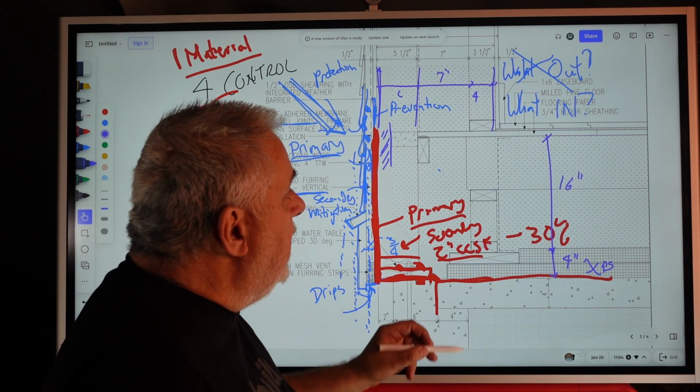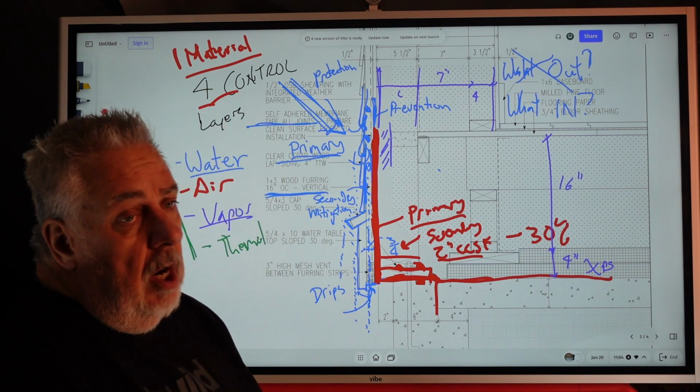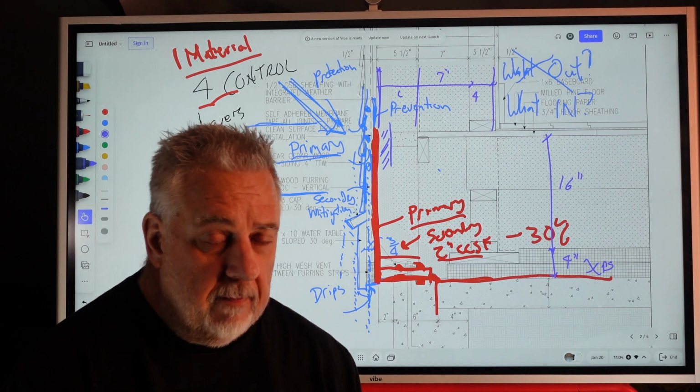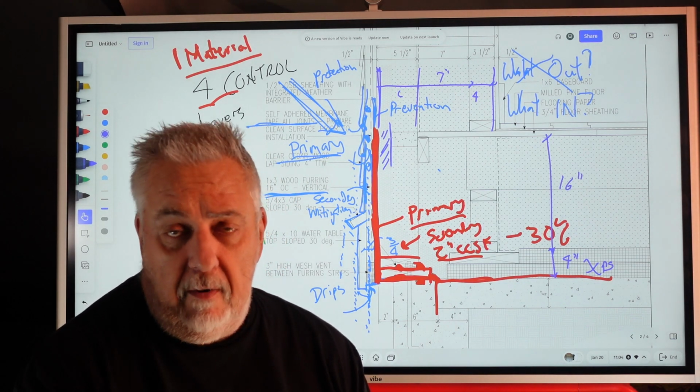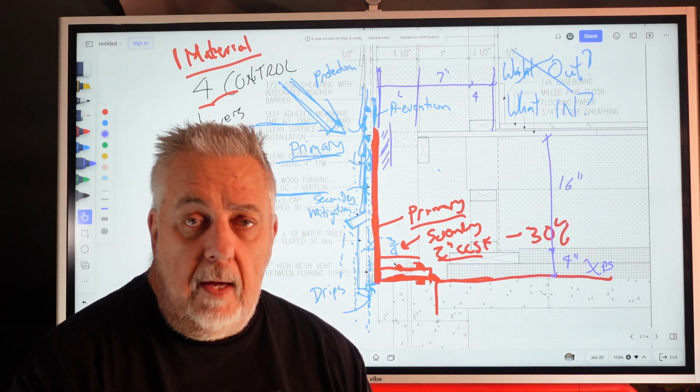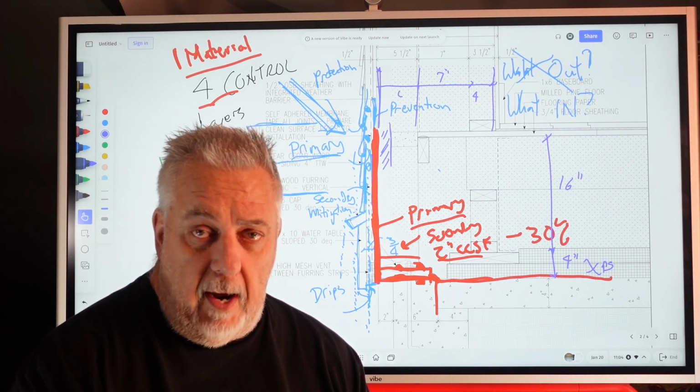Right? So the idea is that first, we control the amount of moisture inside the house. So we have a fully functioning ERV in here on a duty cycle that maintains the relative humidity in the house, right?